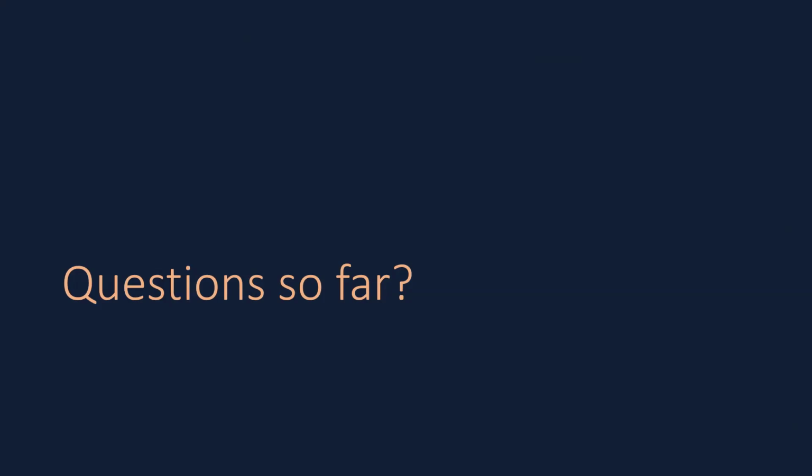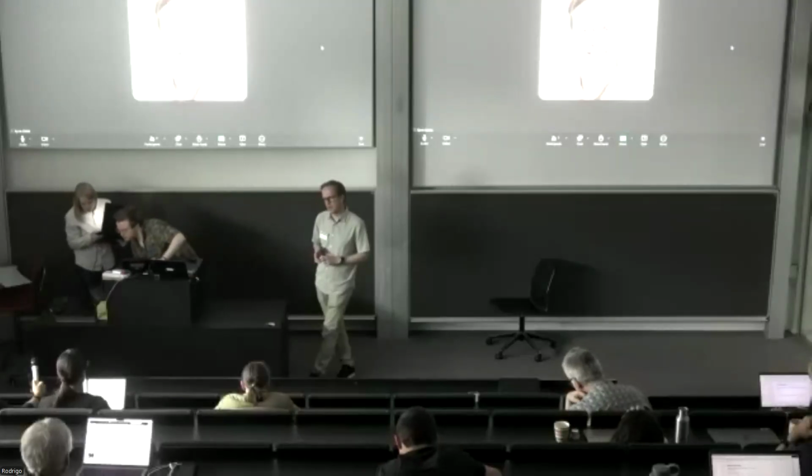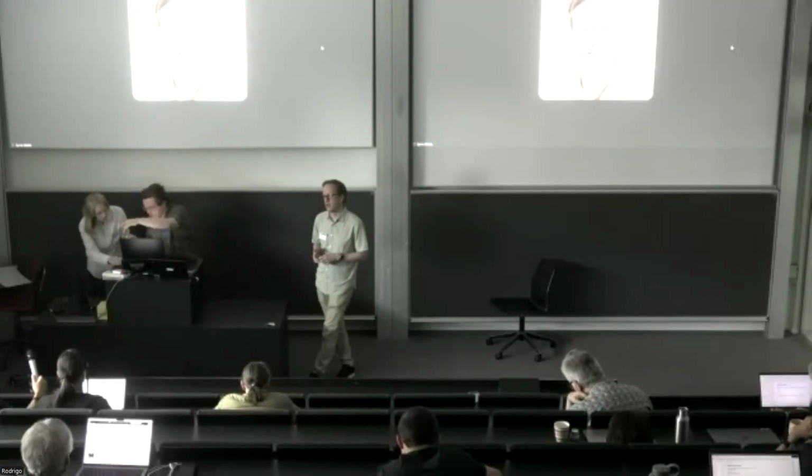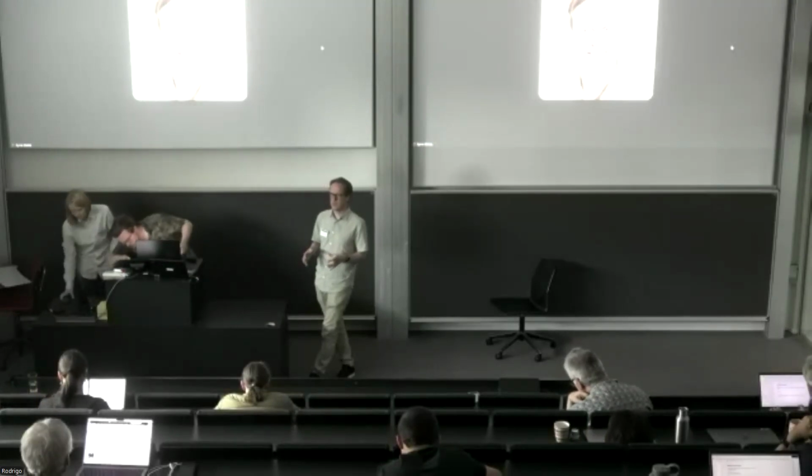Yes, so in simulation, I mean, there should be values of at least approximating how much energy the robot uses. But in many of our projects, we tried to incorporate that into the simulation, but it hasn't really worked that well, and we ended up skipping that. And maybe thinking about other proxies like the mass of the robot or number of joints that could somehow say something. It's not really that good, but I don't see why it shouldn't be possible to get it out if you just know enough about your physics simulator and work a bit on that problem.